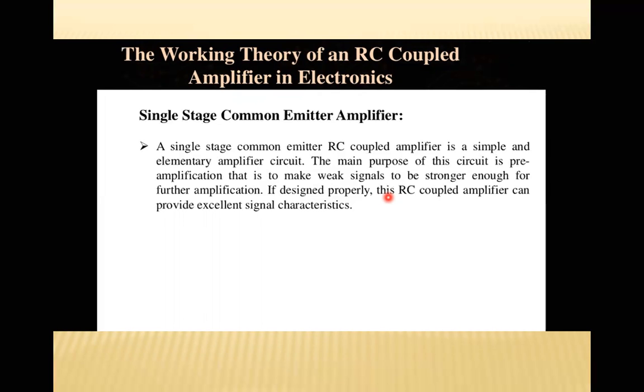Let's go through this. A single stage common emitter RC coupled amplifier is a simple and elementary amplifier circuit. The main purpose of this circuit is pre-amplification, that is, to make weak signals strong enough for further amplification.